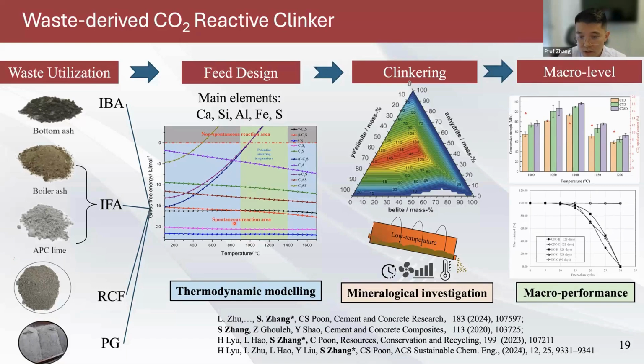And we do the mineralogical investigation by actually clinkering the cement. Then we validate our cement using macro-level performance. Strength is the number one rule of thumb, the number one criterion for our clinker. Also, we tested the durability performance of our clinker and new cement as well.